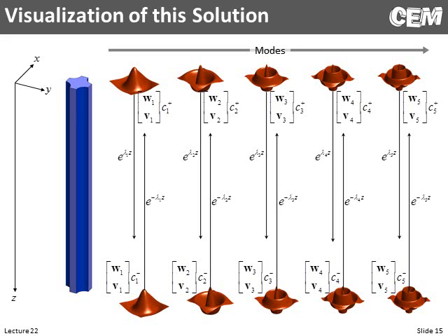Another picture that's exactly the same is trying to illustrate what's happening inside of a semi-analytical method within a layer. So we've essentially analyzed the cross-section, and we calculate all of the modes that exist in the cross-section. Our modes, or the picture of the fields, is described by an eigenvector for the electric fields, an eigenvector for the magnetic fields, and that just tells us on a relative scale what all the field components look like. We need to know the overall amplitude to know how much power is in that mode. And each mode gets its own amount of power.